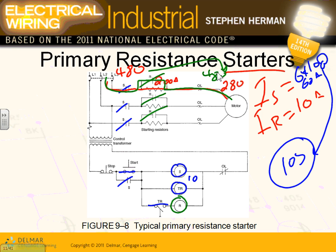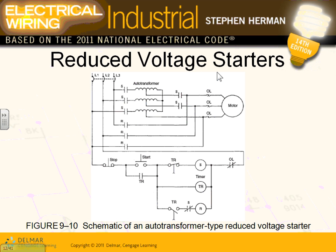Any question, guys, about this? They call it primary resistance to reduce the voltage. I don't know if you did it with Gary, guys, in our labs, we have multiple motors that we wire here. The second one that does the same thing is an autotransformer. The same principle. You push the button here, you energize this coil, right? So you energize the start coil, and you energize the timer here. So this will close to hold it, right? So we're holding. So S, bam, bam, bam, and all the S's are going to close.